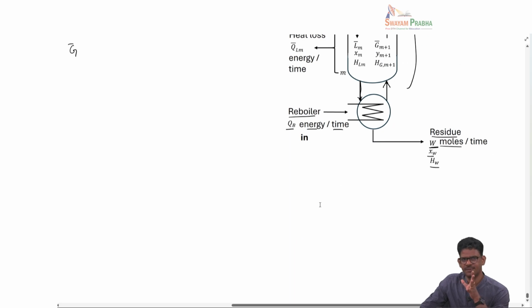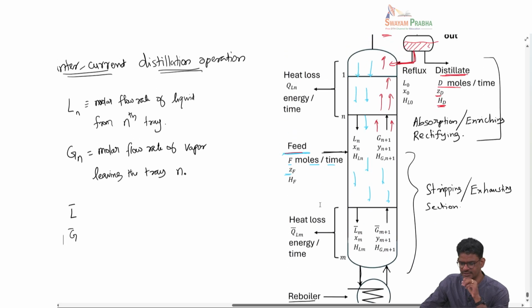So from the design point of view, what we would like to know is, like in the absorption column, the number of theoretical stages for a particular separation operation. If you want to calculate the column diameter, then we have to invoke the concepts of pressure drop for two-phase gas and liquid flows, and we have dealt with this in absorption column problems.